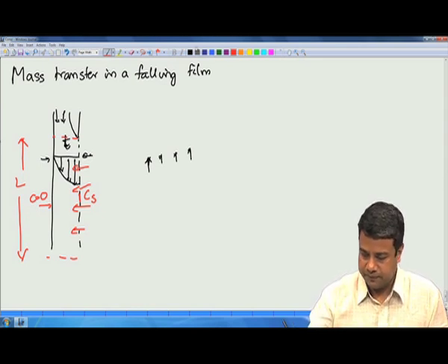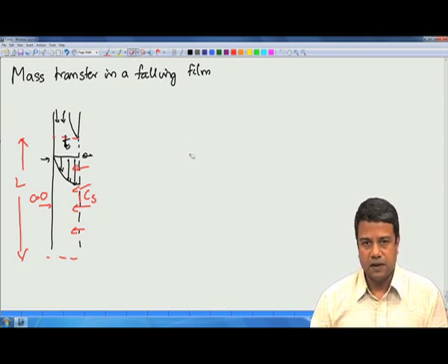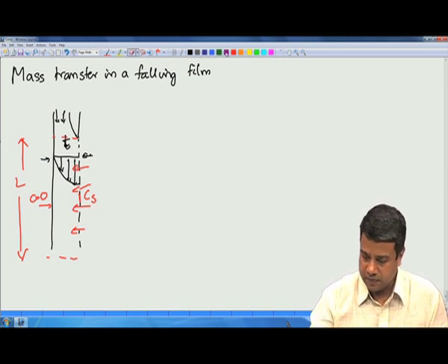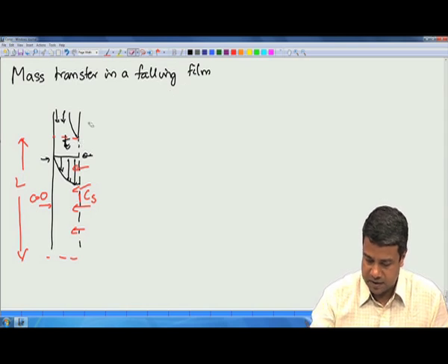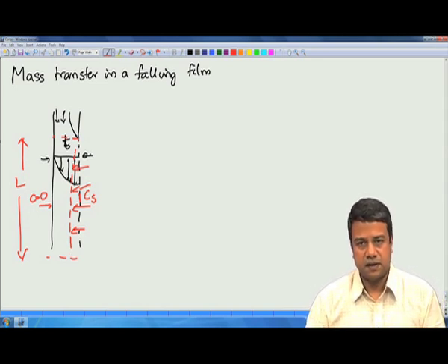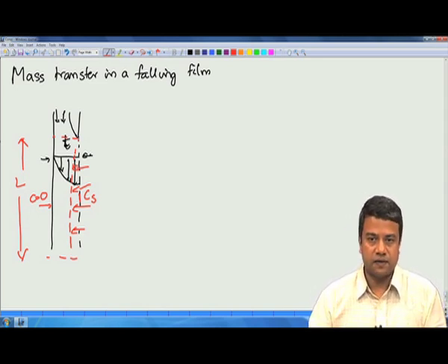Now, this problem we can idealize as the flow in an infinite film of fluid, provided the penetration depth of the gas within this fluid is much smaller than the total thickness. In that case, it looks like the flow through an infinite fluid.